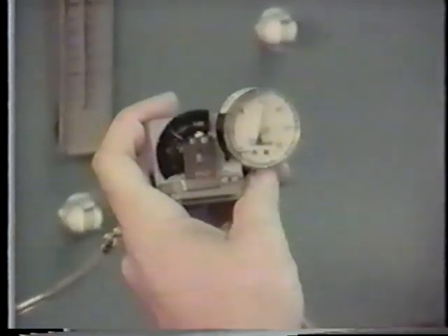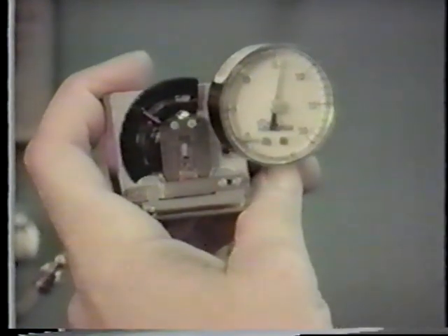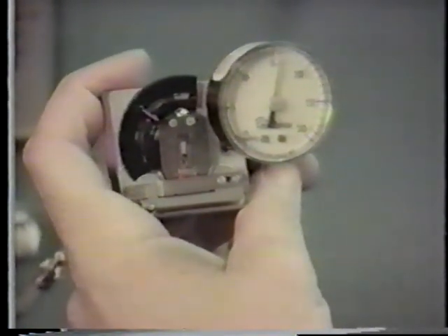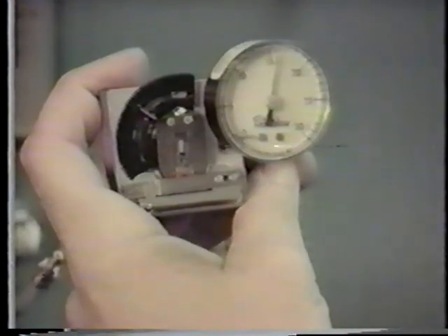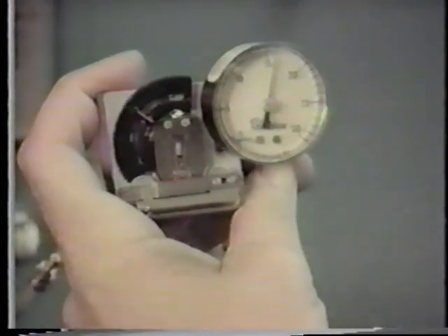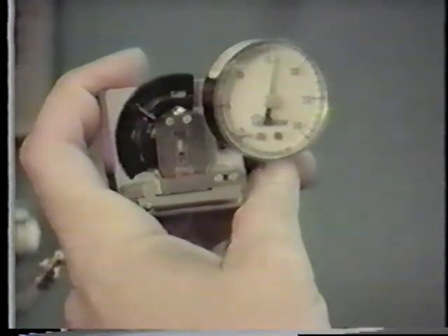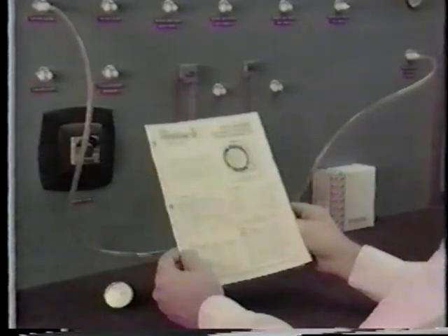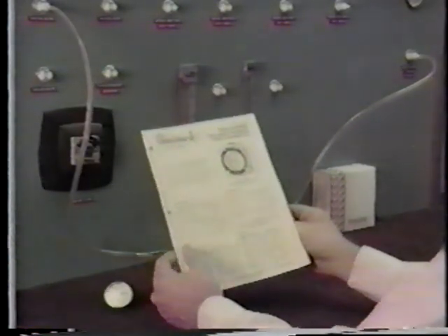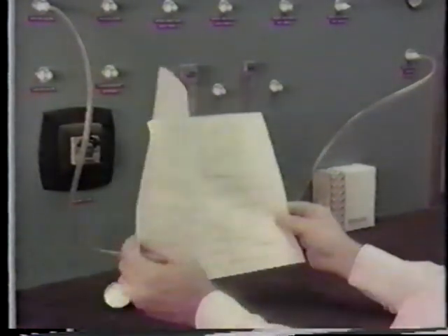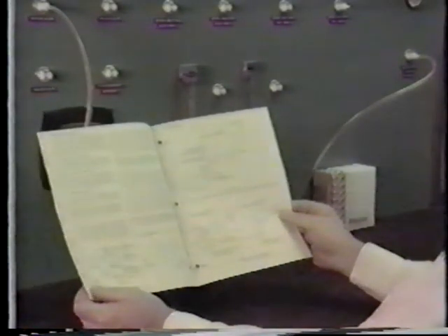It is also necessary to read the branch line pressure while making the switching adjustment. The sequence of adjustment varies slightly depending upon the model thermostat used. Here we will go through the sequence of adjustments for the direct acting model. The complete calibration procedure for all day-night thermostat models can be found in the 2214 series datasheet.